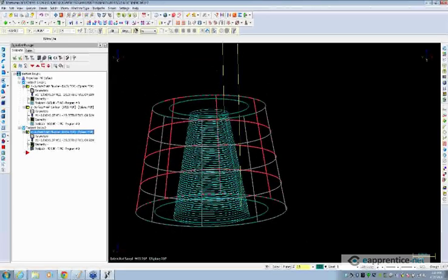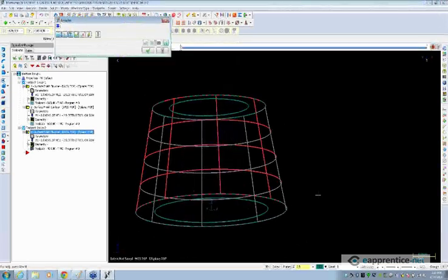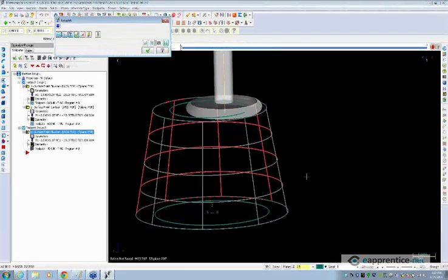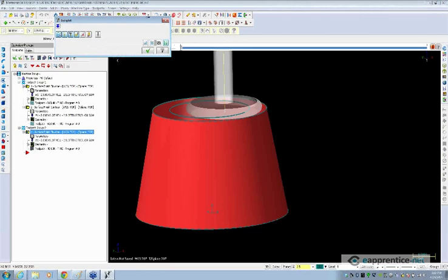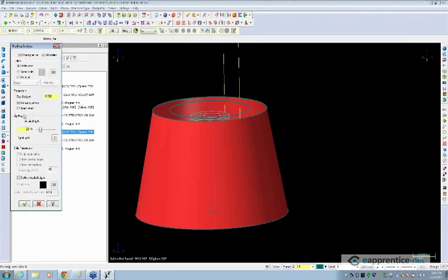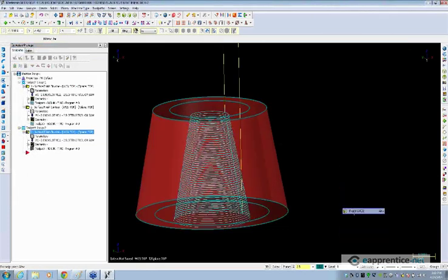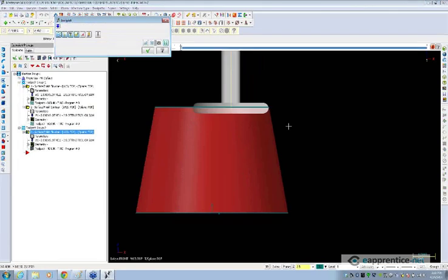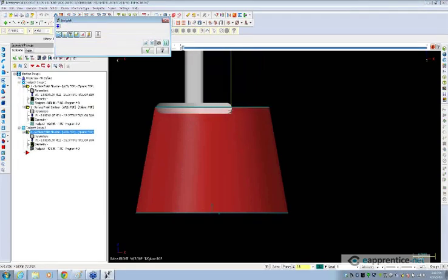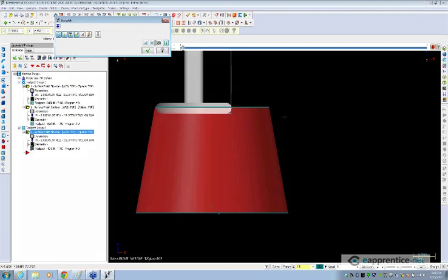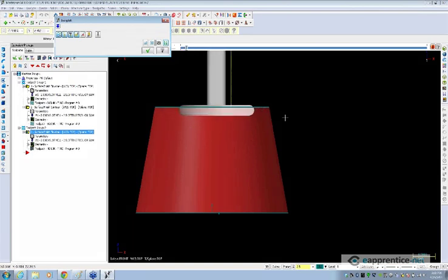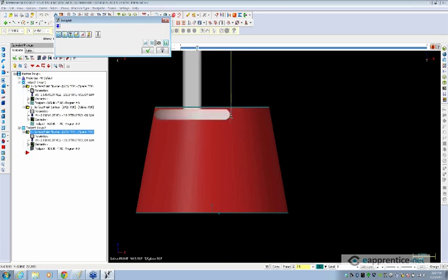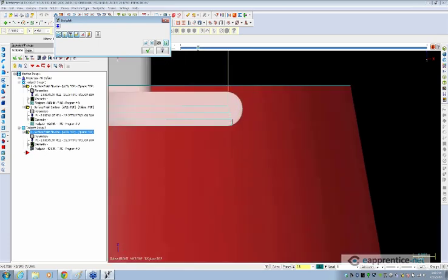If we look at this surface finish flowline, and we look at it in backplot, here we're starting on our surface, and actually let me change translucent mode so we can see this. All right, if I backplot this now, you can see that we're starting out okay. I don't like the direct plunge into the cut, but we'll worry about that in a minute. And now, as we make our passes, there's slice 1, there's slice 2, and you can see that it's just making these cuts along the surface and then doing this direct feed motion.